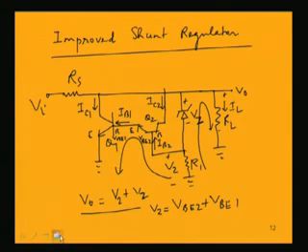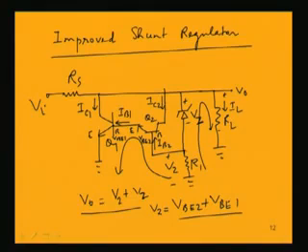As V2 increases, VBE1 and VBE2 both increase, because these are almost similar type of transistors. So the base to emitter voltage rating for the two transistors will be similar. Now what will happen if VBE2 increases? Then the base current in the second transistor increases, so IB2 increases.